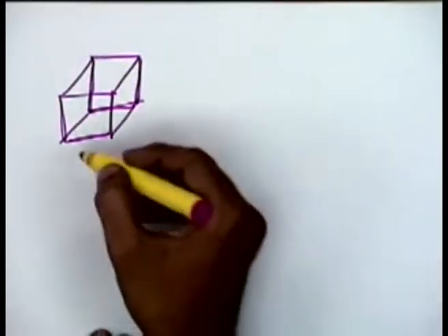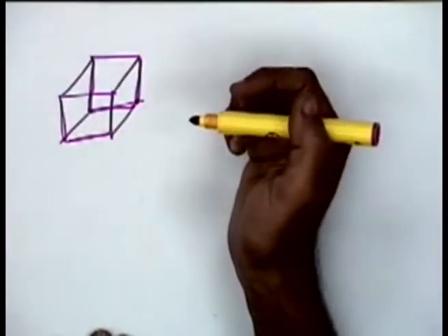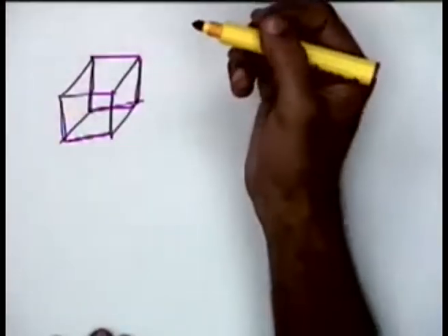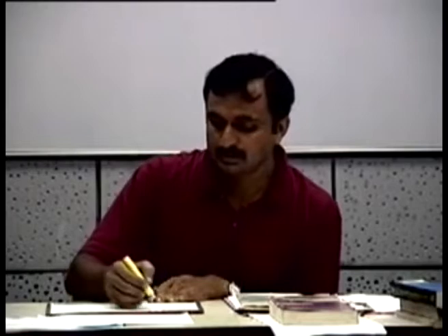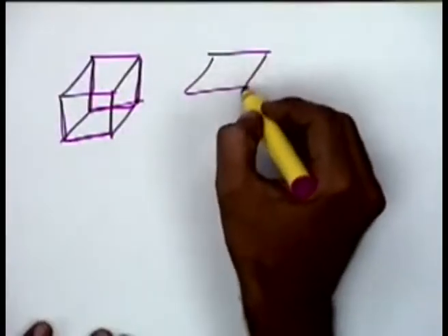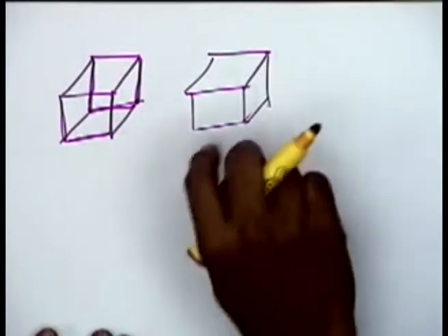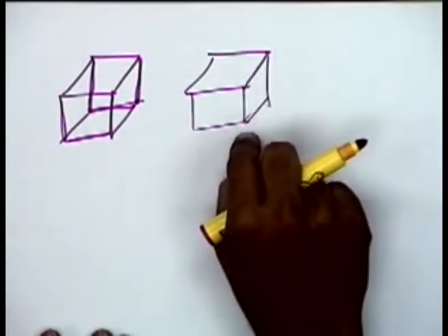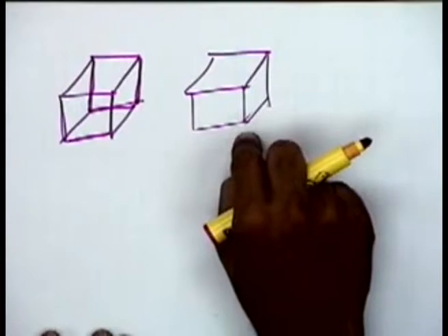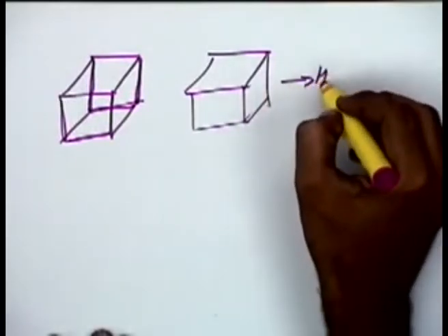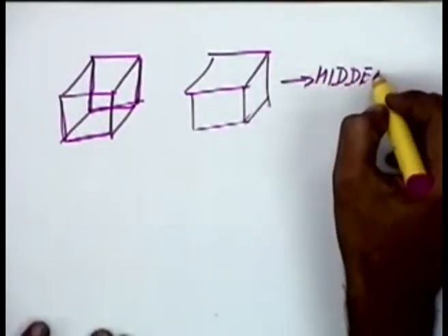So normally we like to remove the hidden surfaces, the surfaces at the back which are not visible, the edges which are not visible. We like to remove those lines and edges. So instead of drawing it like this, we like to draw it just like this. This would improve the clarity of the presentation. It will help in visualization. So when you are talking of display, we like to remove hidden lines. Okay, this is normally referred to as hidden line removal or hidden surface removal.